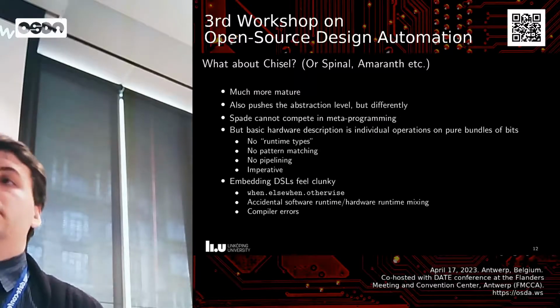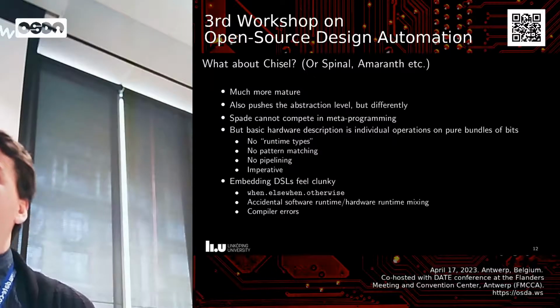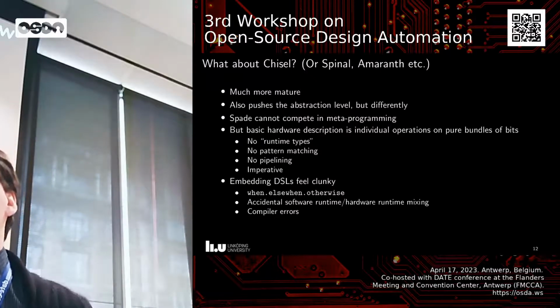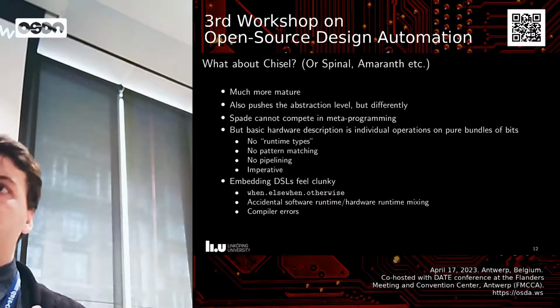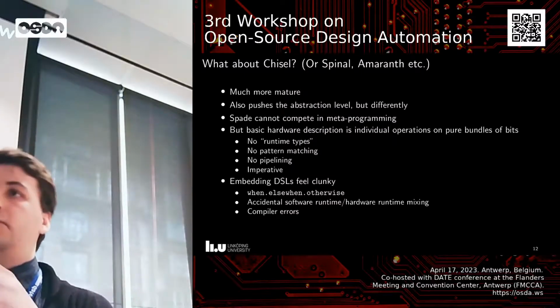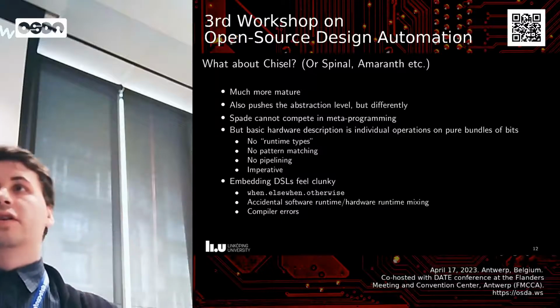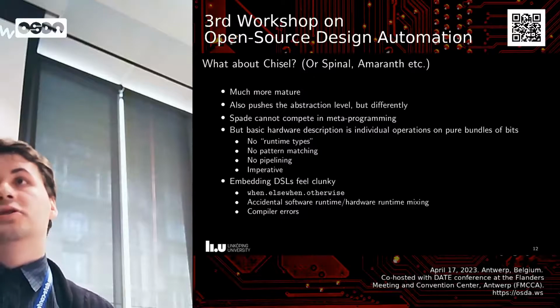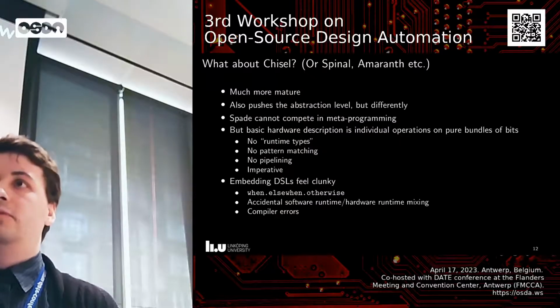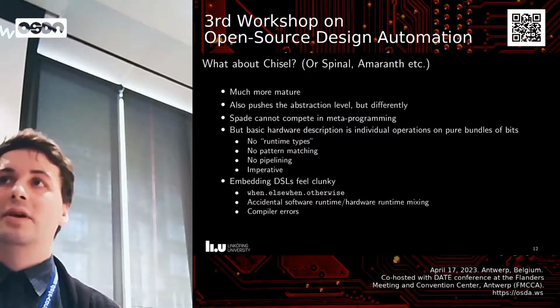Yeah. The answer is I want control of the retiming, I guess. The reason I started this project was I was doing a bunch of pipelining stuff, and if you're doing it in Verilog, you do _S1, _S2, and then you have to make sure you refer to things. I still wanted that level of description. I just didn't want to do the work manually because it seemed so easy to automate.